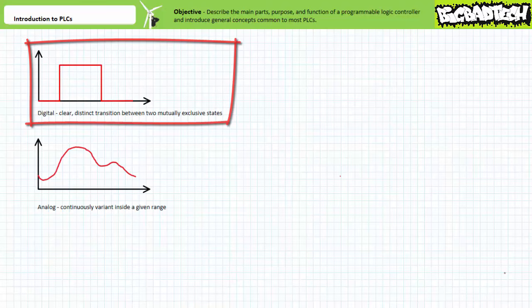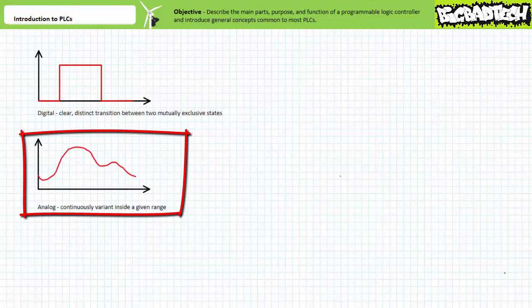An analog signal, in contrast, is one that is continuously, infinitely variable inside a given range. A pressure sensor would be an example of an analog input in that it sends a proportional electrical output based on input pressure. More pressure results in more voltage. This analog signal can be analyzed by the CPU, and the PLC can respond appropriately to pressure conditions inside a specific range.